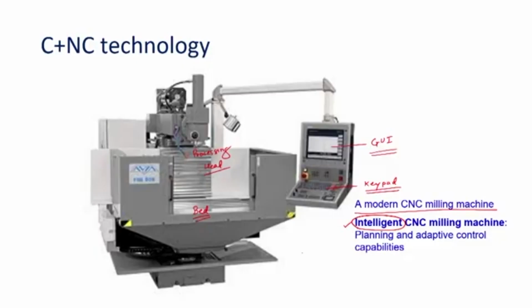In this case, the machine tools are equipped with safety sensors and process monitoring sensors such as temperature sensors, force sensors, and limit switches. It is very important nowadays to have limit switches for the safety doors. When such operations are being carried out at a high energy input, and if something is not proper with the machine tool, the sensors give input to the controller, and the controller takes action accordingly, or it gives an alarm to the user. So, in that sense, all the machine tools are nowadays intelligent machine tools.